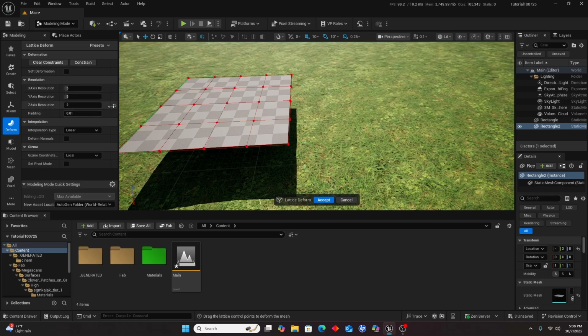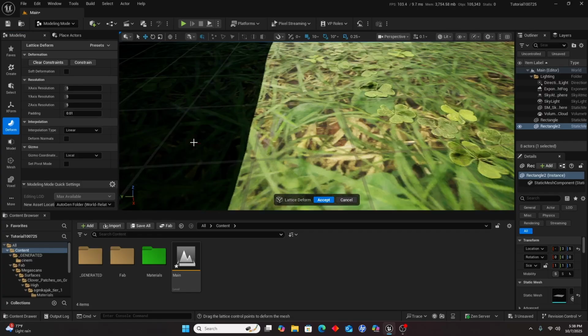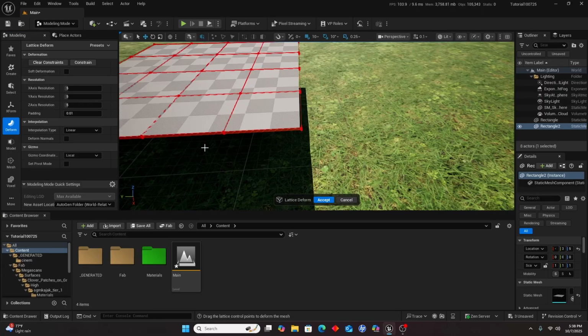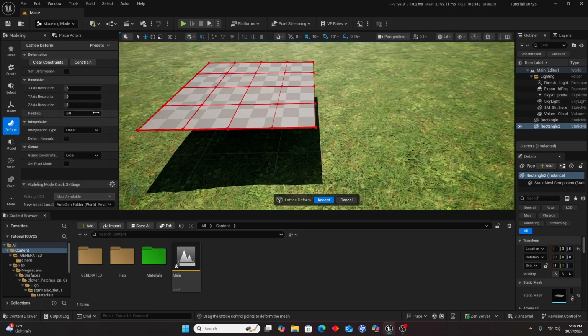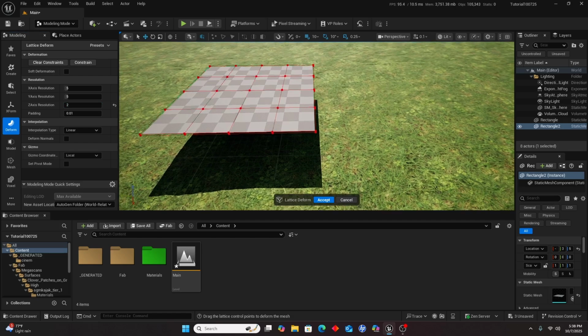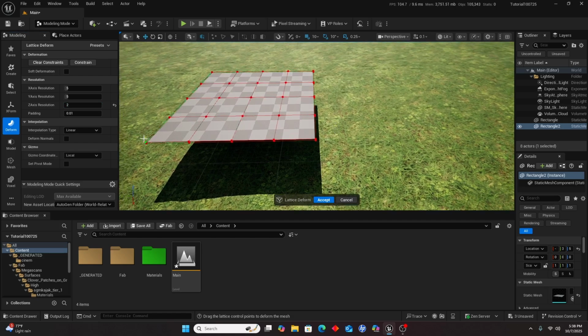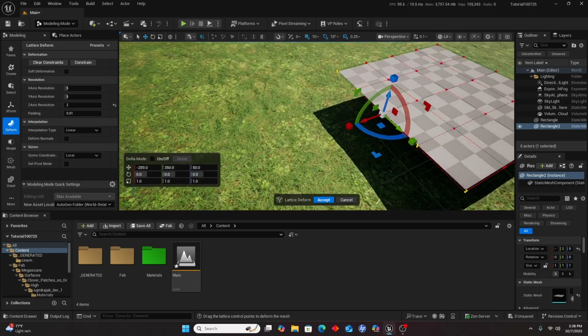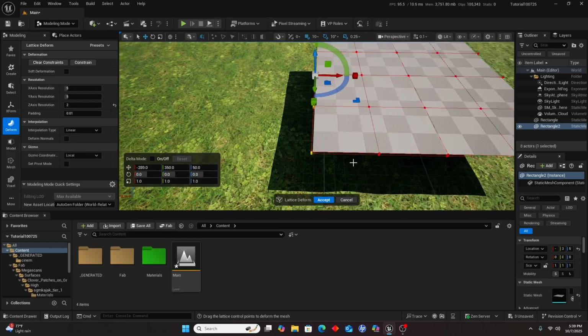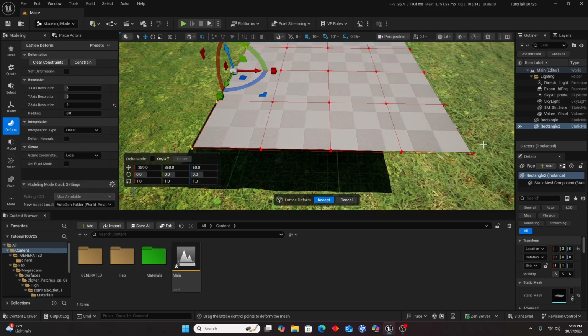In my case, off the truck, this will come up with 5 vertices here at the end. Honestly, I don't think it matters what you set this to. 2 is the least you can set it to. You cannot set it to 1. But ultimately, what you're going to do is shift select all of these edge vertices right here.